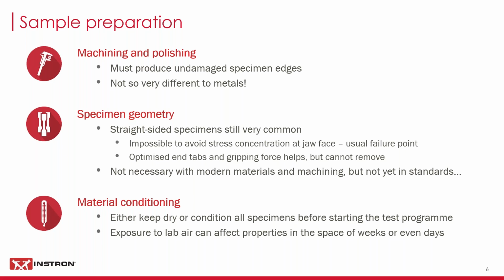So you have to condition the specimens, whether that's by sitting them in a constant humidity chamber for an amount of time, or whether it's keeping them in completely dry conditions. You need to think about it. One quick comment on that: the fatal mistake that people make is they put specimens in a plastic bag and think that will stop them absorbing water. And it doesn't. It will keep them clean, obviously, but an ordinary plastic bag does not stop water absorption.